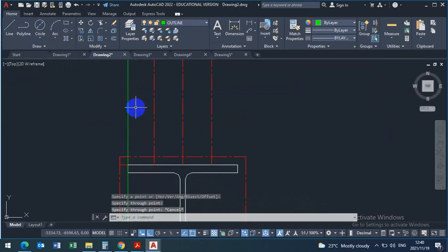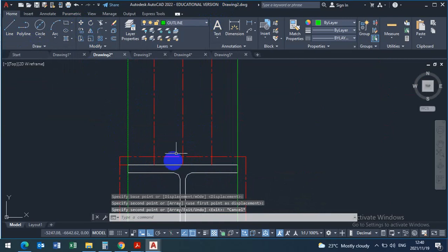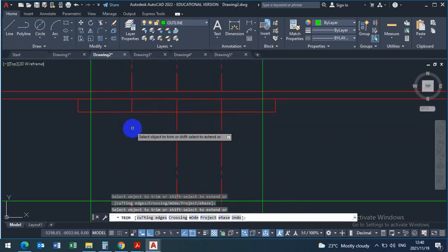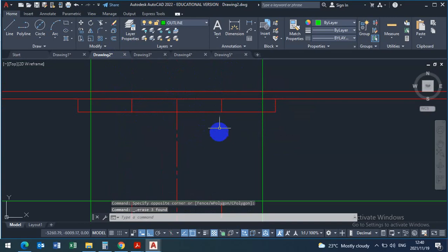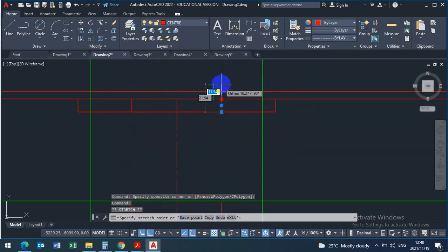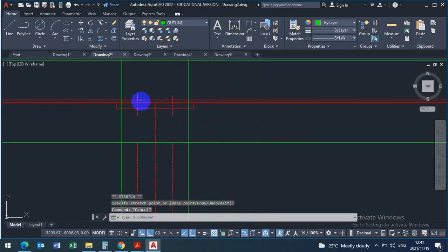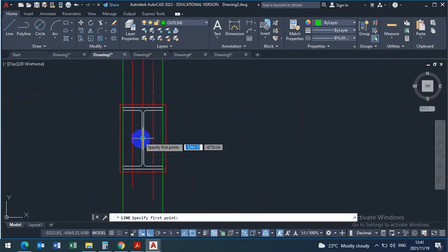Copy. These holes are for the gauge distances, so we can trim them, and when we trim them here, they need to go through the web as well. Yeah, it's fine, I'll delete that. These holes are not only on the plate, they are also on the center line. And because the hole position is 22, just offset these ones by what? 20 is for beam 3. Then we work with the center line somewhere there.